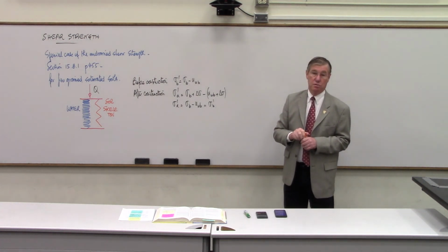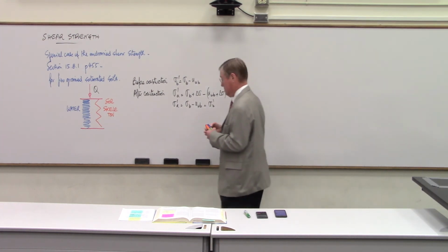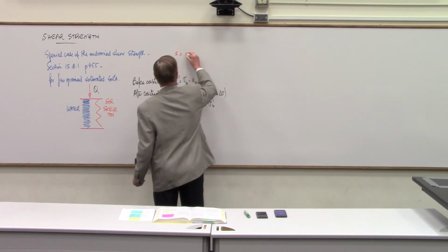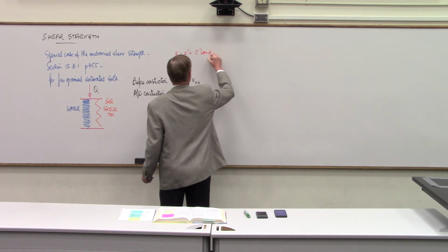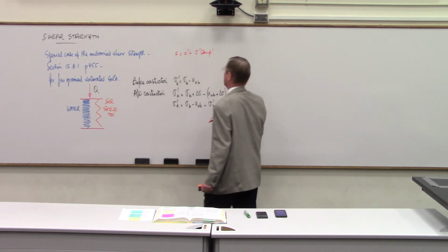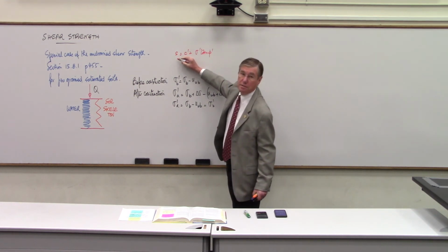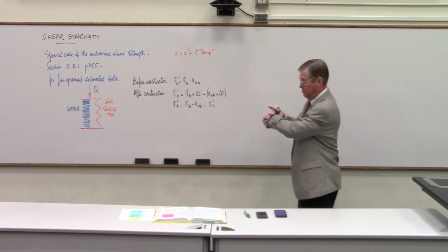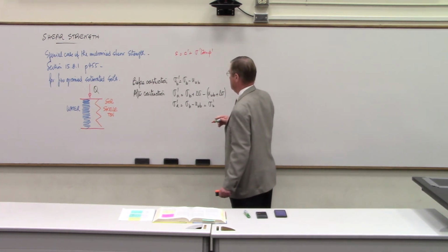And that's bad news, because you remember from the shear strength equation, you remember this important equation, S equals C prime plus sigma prime tangent phi prime, right? This thing. If you don't increase this, you don't increase that. And so that's what's happening with the undrained shear strength in this case.